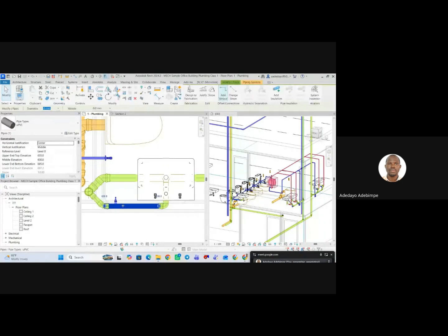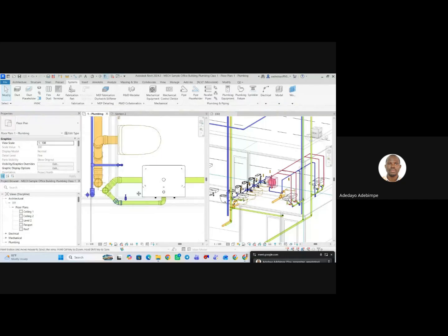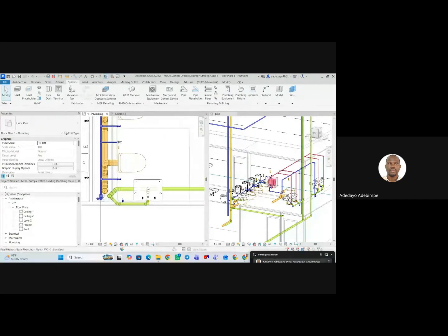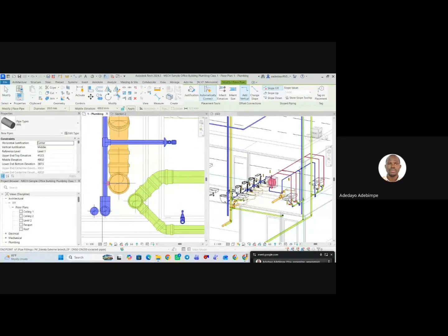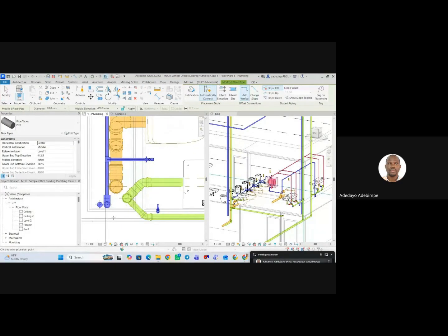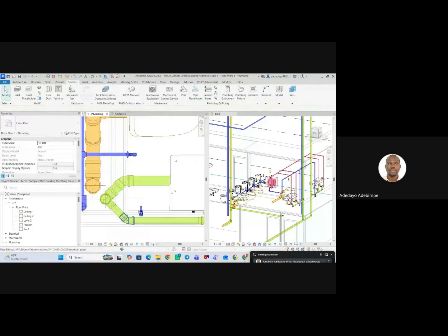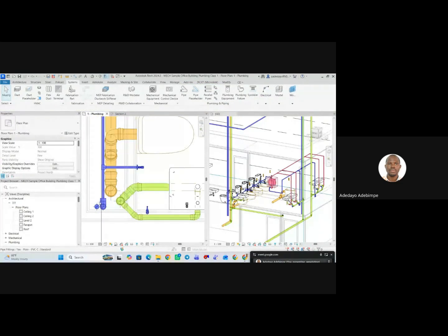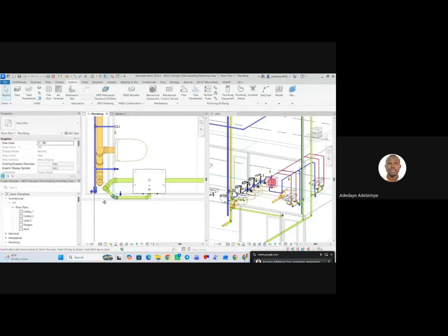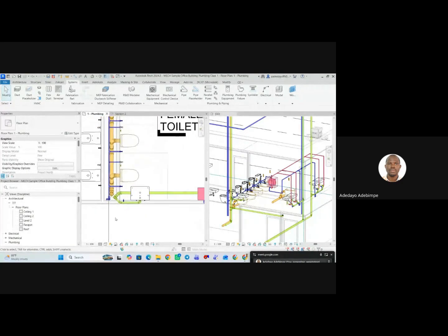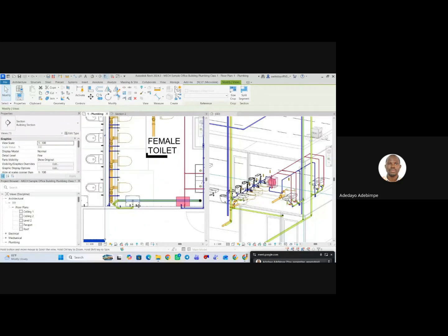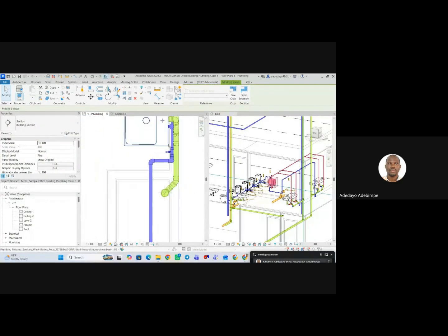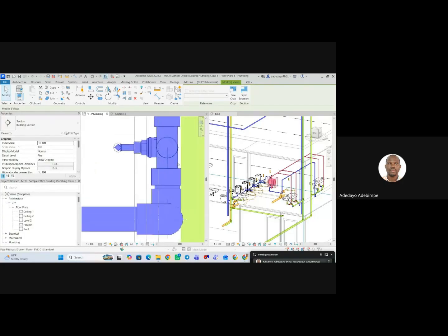Now I need to draw my pipe. So I'll create similar, right click, create similar. Then one trick I can use here is, since this angle valve is close to this riser, I can just bring it direct at low level to enter into it. So let me move my pipe into place.